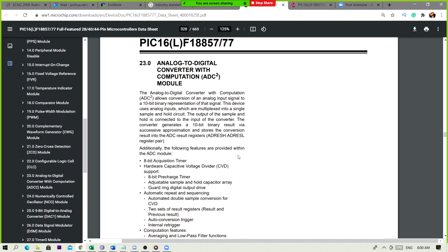Now, the next question you have here in the chat: how to get the values from a modulated input from a port. Well, that's the same story about analog inputs. What I mean by modulating is it changing. Right. So that is the same point, right? You use the A to D converter, right? You configure the A to D converter so it's going to sample from the pin that you have your signal connected to, right? And it's going to give you a number. The number it gives you will range from 0 to whatever the maximum is, okay?